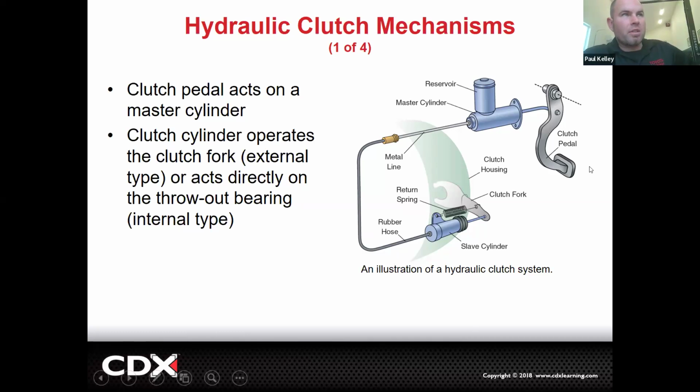You'd throw your clutch pedal 6 inches. 1 or 2 of those inches would be wasted on the actual flexing of your firewall because it's rusted or weak or cracked. That would make the clutch not disengage all the way. Because how we disengage it, we throw 6 inches of pedal travel right here. That becomes 1 inch of stroke in this master. That becomes ultimately 1 inch of stroke on the slave cylinder.